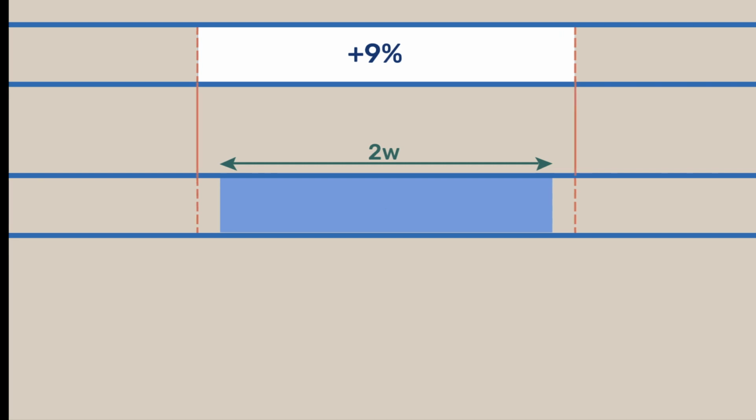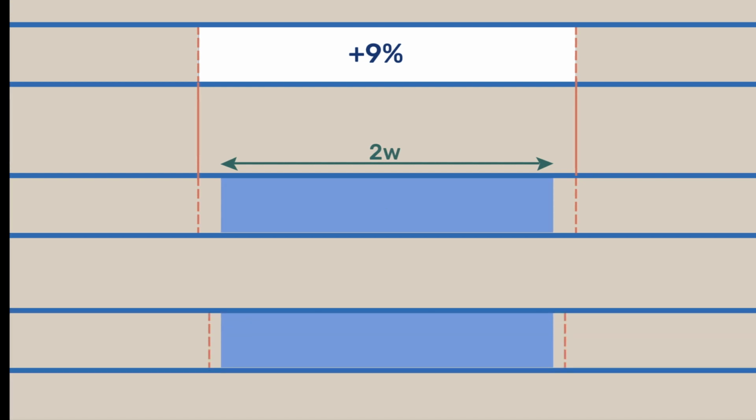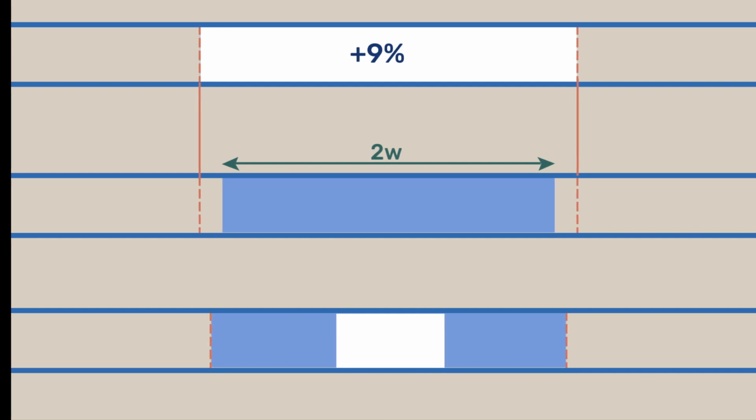Let us consider this process starting with the nucleation of an ice crystal in the center of the water pocket. As this crystal grows, it pushes the yet unfrozen water ahead along the pore. This causes frictional resistance between the water and the pore wall, which produces pressure in the liquid. Indeed, because of its viscosity, water partially resists being pushed through the porous network.